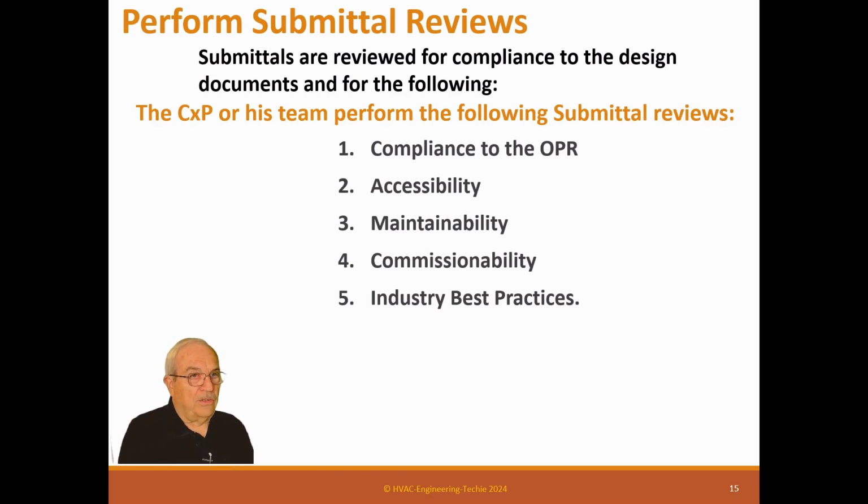Yours are totally different. Yours is now, is this system the right size? Can it actually be accessed where it's going to go? Is it maintainable? Is there anything here? I've had jobs where you can't get the filters out the doors. So it's not maintainable. Commissionability, can we actually commission this? And normally it's always yes, but you need to make sure. Can it be tested and balanced? Is there enough things in there for the TAB to happen? And is this system the best for industry best practice?